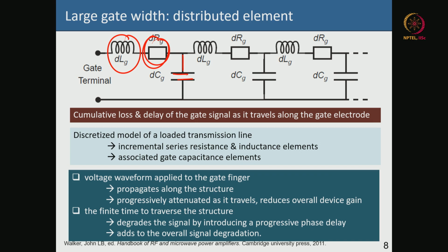The gate will have a capacitance coupling to the channel. So, that capacitance is in parallel to the gate metal, which behaves as a resistor, and it also behaves as an inductor, because it can store magnetic energy when an electromagnetic wave is coming. So, a straight line or metallic line or a wire is also an inductor. It does not have to be a wound wire, it can be a straight wire, it will still have inductance. So, the inductance and the resistance, and this is the delta Z, this is delta Z. So, you have many elements, you model the gate something like that.